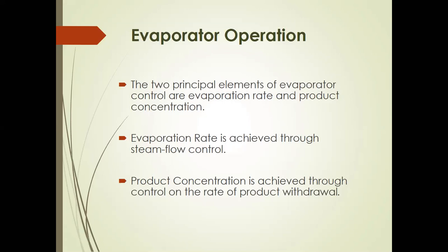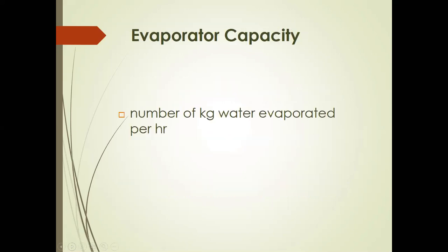Meaning, it evaporates only once, then you get the concentrated product. So in the case of an evaporator which has a pool of concentrated liquor inside, prolonged heating allows us to improve the concentration of the product. So that's how we control the concentration of the final product for the evaporator.